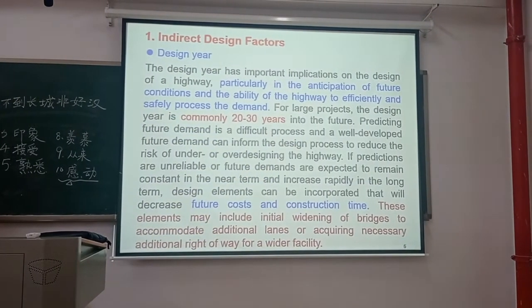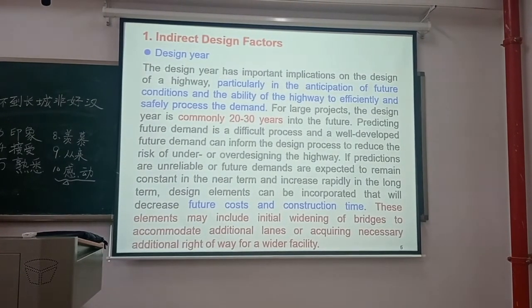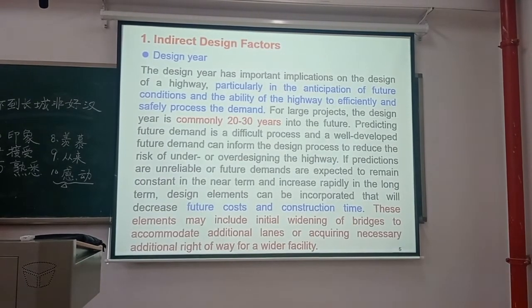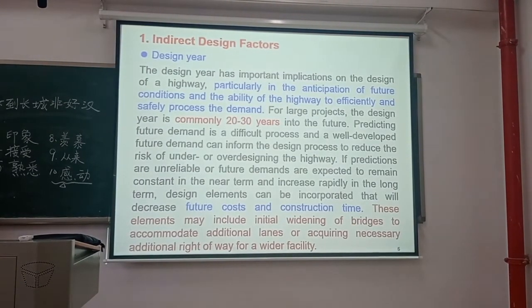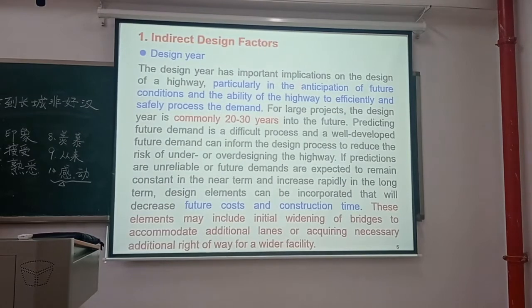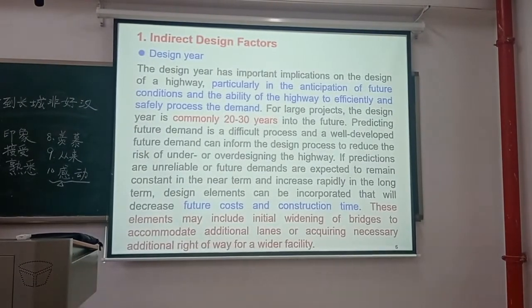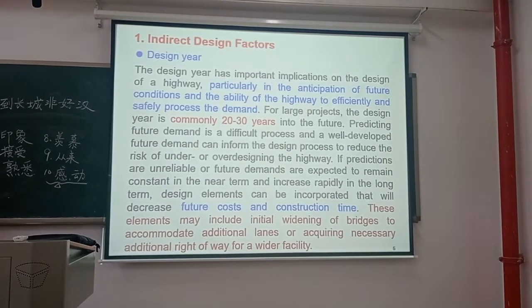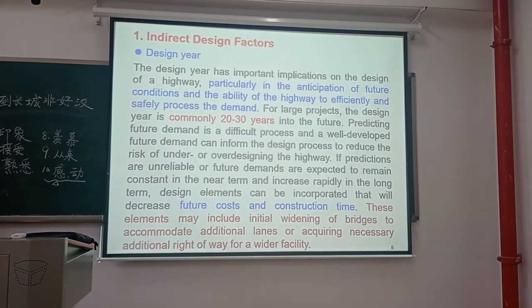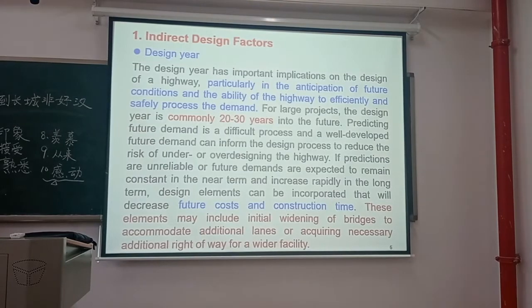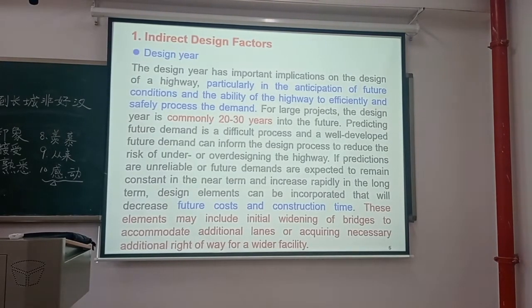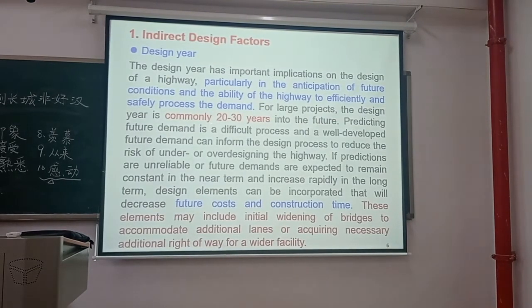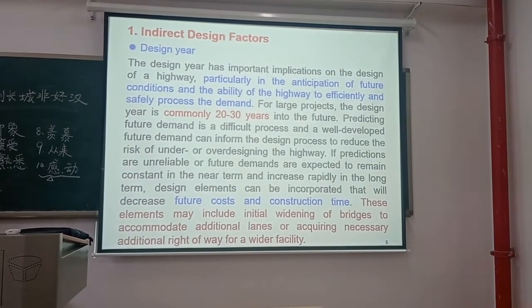Design year. Design year has important implications on the design of a highway, particularly in the anticipation of future conditions and the ability of the highway to efficiently and safely process the demand. For large projects, design year is commonly 20 to 30 years in the future.